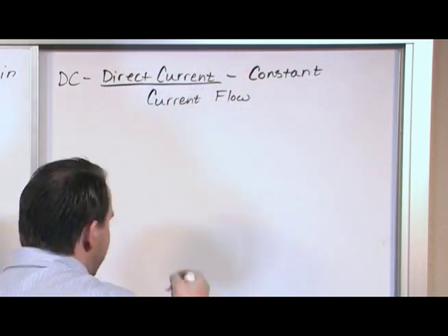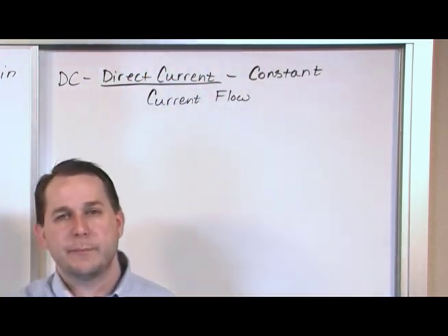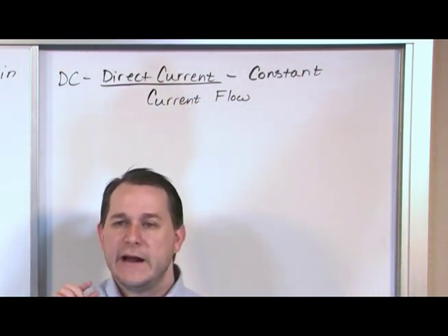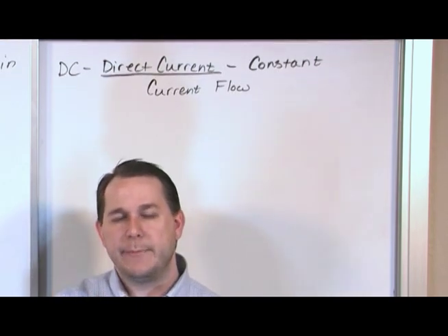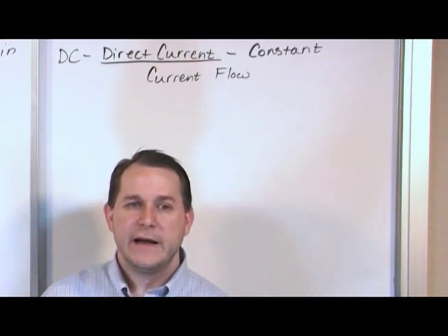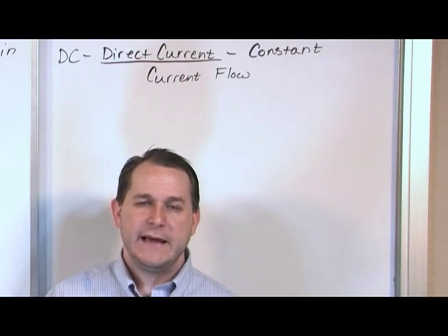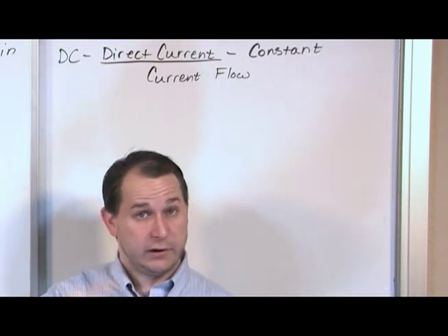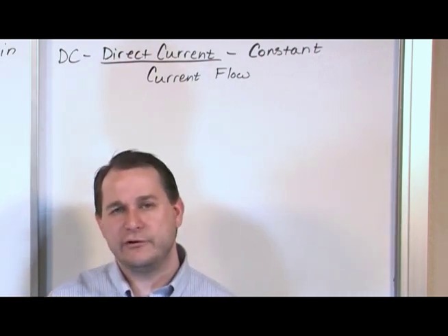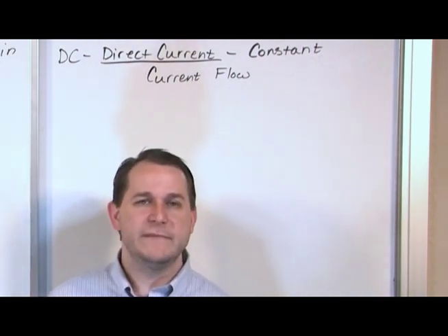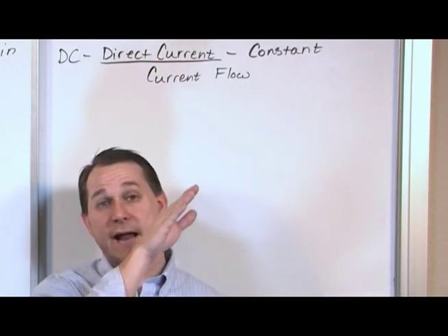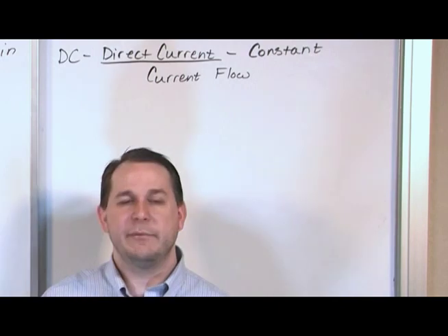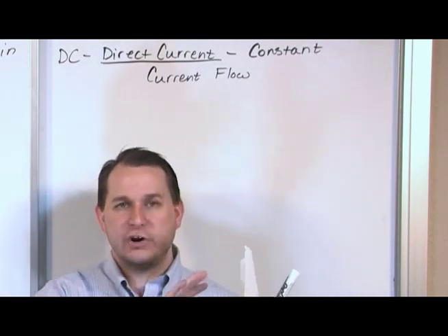Basically, all of the batteries you've ever used in your life, the AAAs, the AAs, the 9 volts, watch batteries, anything built into a little device that we call a battery, always generates a direct current. It means that when you hook it up to the circuit, it's giving you a constant voltage at the source location that's pushing current around. And because it's providing a constant voltage, the current that comes out is constant, never changes. Now, in reality, the battery is going to die down and get weaker and weaker, so the current does eventually bleed off. But if you take a snapshot and look at it, the current is a constant.